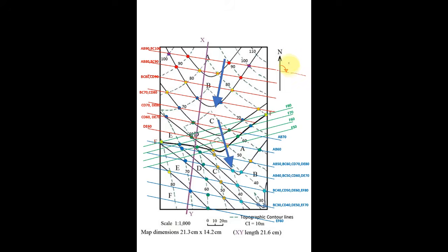You can either write it as a whole circle bearing or a quadrantal bearing. Same is for this fault line as well. For the fault line also, you can extend this north down and measure this angle. That angle would be your whole circle bearing angle, or in quadrantal it will be north, theta, east.